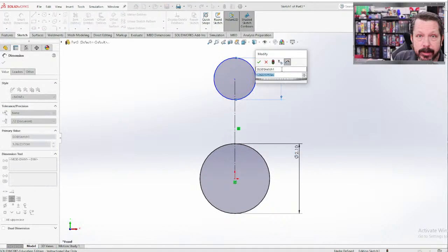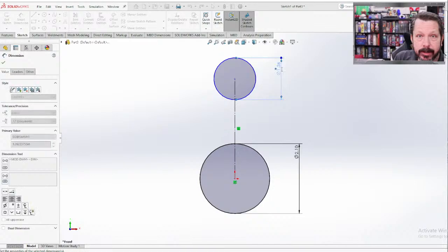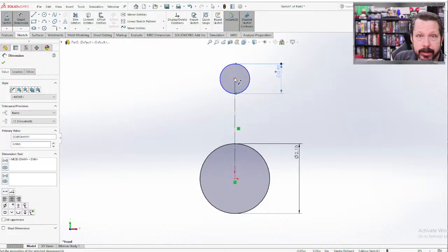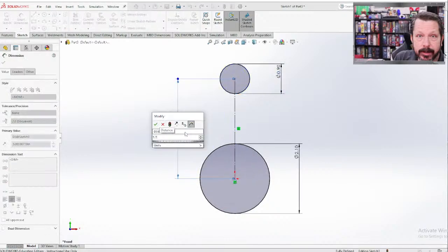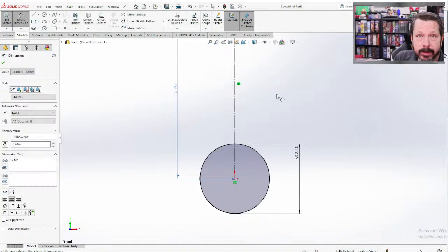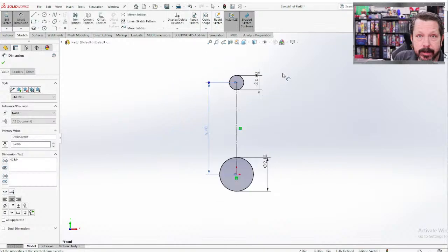Let's give it a dimension of 0.9 inches. Okay. And then from center to center, the rod length here, we're going to give 5.7 inches. So this is roughly the dimensions if I were creating something for a V8 Chevy 350 engine, somewhere in that range. These are not specific to any particular thing, but this is about what you would expect.